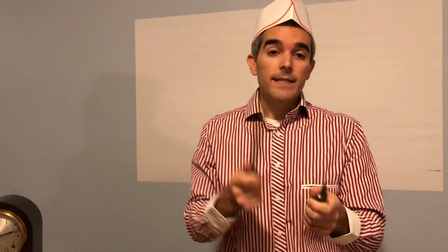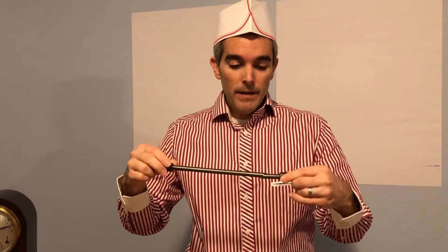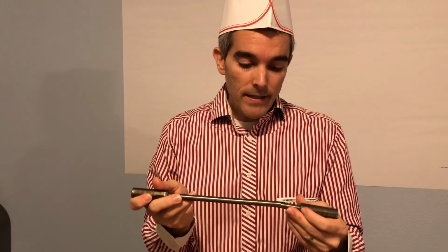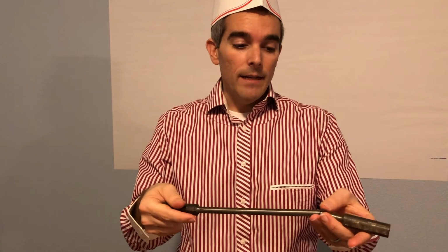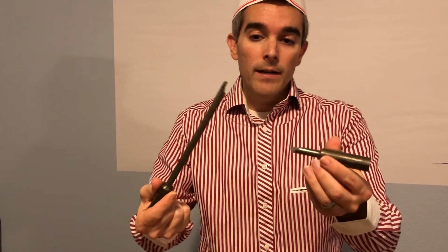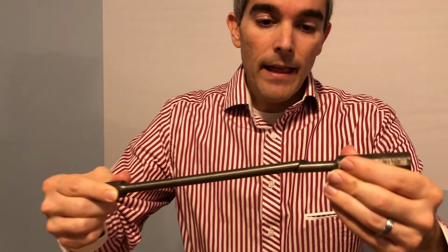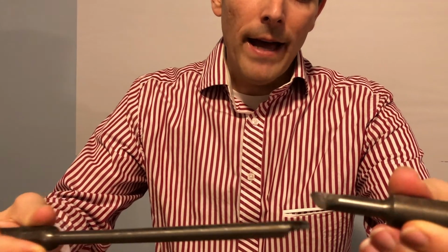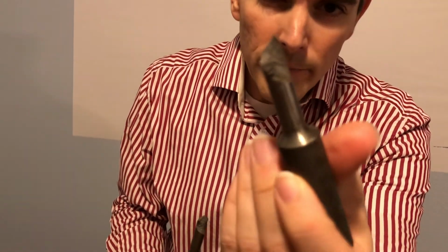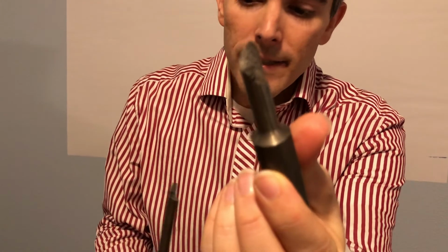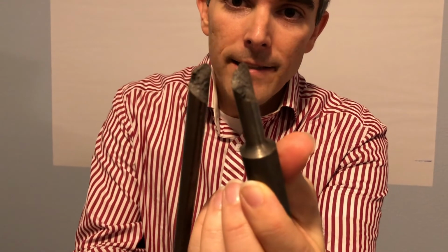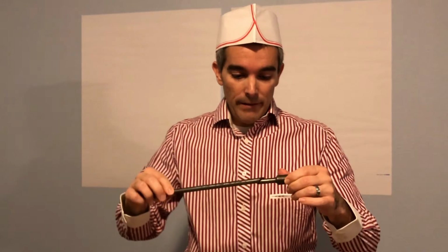If you just want to see another example of a torsional failure, this is another torsion specimen. This is much like our tension specimen, except we would grip this in a machine and we would twist it and break it in torque. Here again, you can see a little bit of a helical pattern. If you zoom in, hopefully you can see that it has a very rough edge to that surface. That rough edge tells us it's typically a fast fracture. It wasn't very ductile. It was a very brittle fracture because it just suddenly went and broke.